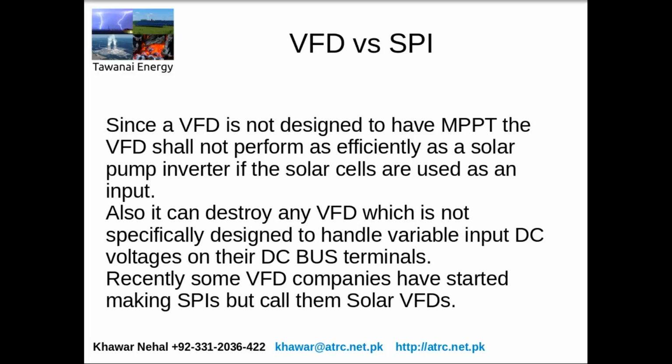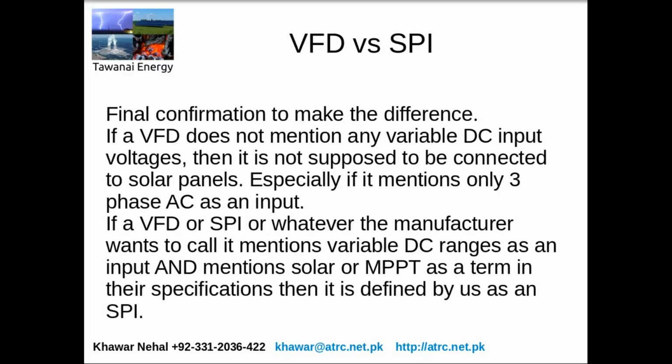Recently some VFD companies have started making solar pump inverters, and they still call them solar VFDs. So you have to be careful of what your VFD is. The old term is VFD, the new term is solar pump inverter. So to make sure that your VFD can actually handle solar panels, look for the word solar or MPPT as a term inside the specifications.